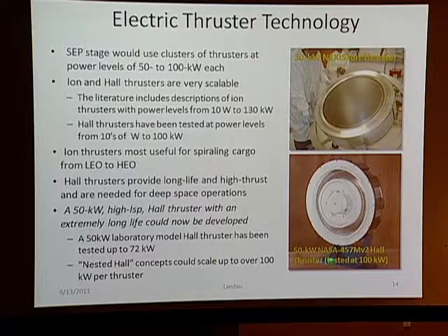And not only that, the main thing that wears these guys out is the walls of these things erode. But because it's a plasma and you're actively working the magnetic field, you can basically design it so that it doesn't wear out as fast. So you're able to sort of reuse these types of thrusters. The solar arrays degrade sort of gracefully. So once you develop a big solar electric propulsion vehicle, you can reuse it over and over again, which can help with program costs and mass and all of that.